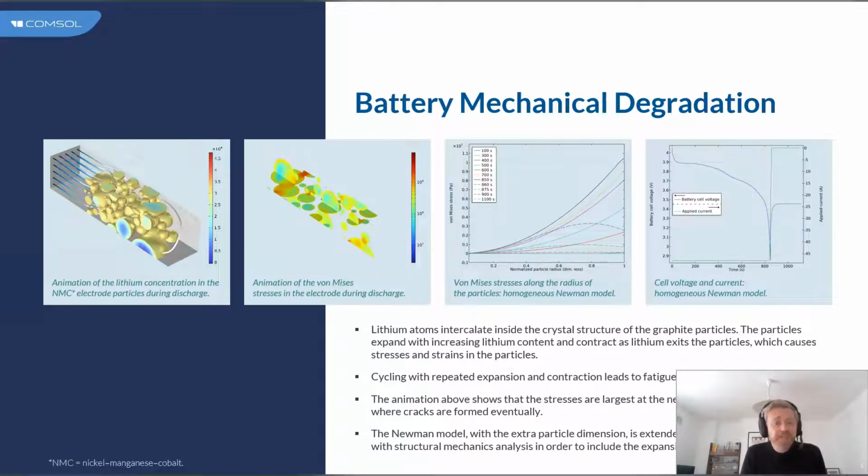Now, within a battery, if we have the buildup of lithium ion particles within the crystal structure, what we can end up with is a scenario where the buildup is essentially causing this to expand, which will cause stress buildup and strain buildup within these particles.